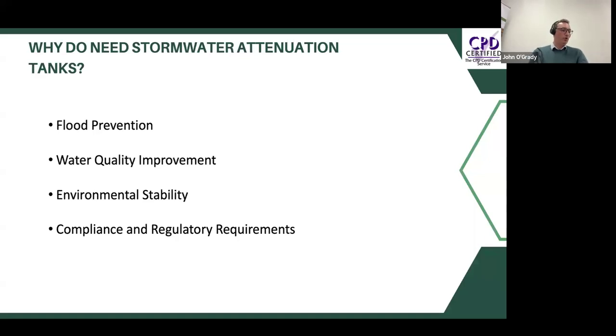It's also important to note that the building authorities in Ireland and the UK stipulate a restriction of stormwater discharge, so that, on a developed site, it can't change the original state of the greenfield condition. So that's the main purpose of where it comes in.